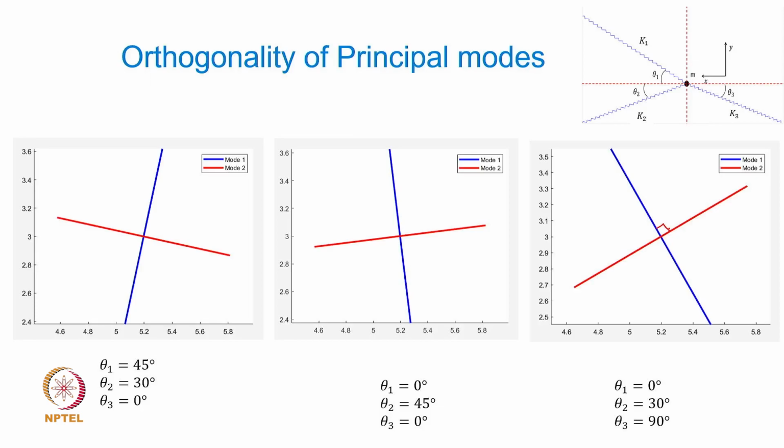That's precisely the meaning of that, and it's quite similar to the case of the principal stresses and principal planes that you might have studied in solid mechanics, where a stress element, when subjected to applied stresses, has planes along which only the normal stresses act, and those two planes are again orthogonal to each other.